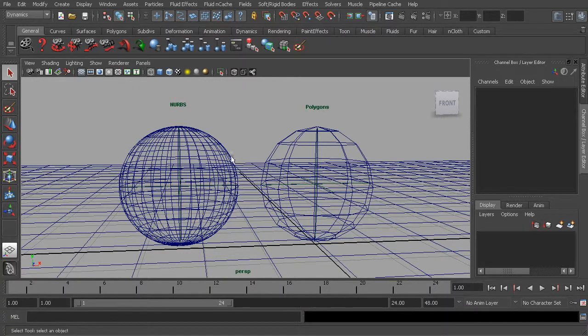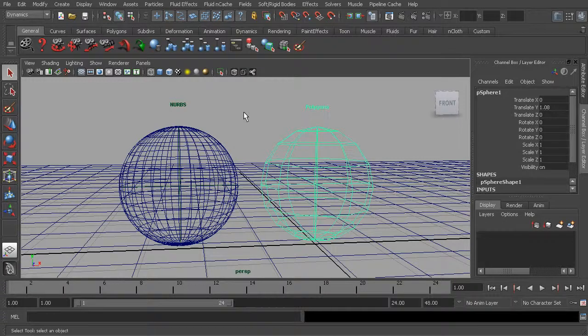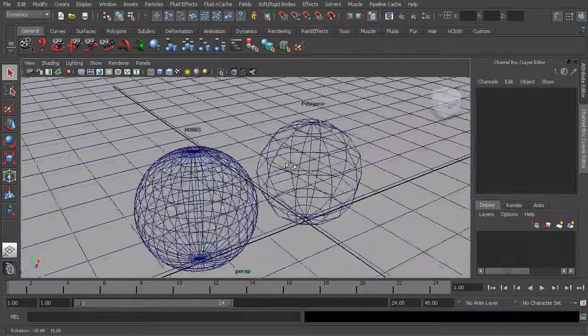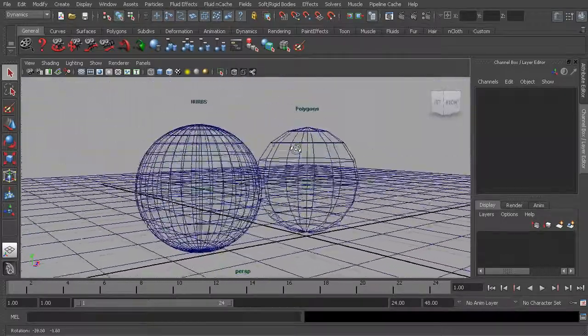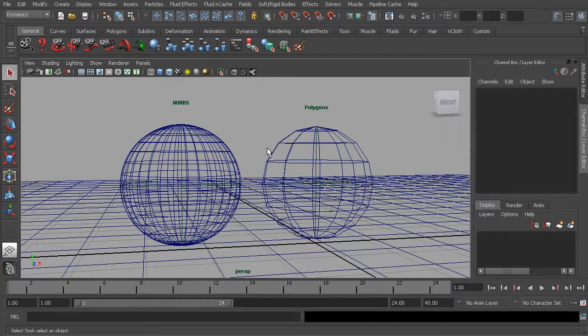Now, up to this point, we've been looking at objects in the viewport in this simple wireframe mode. Now, this is going to be the default shading method in Maya, and to switch between this wireframe and some other shading methods, we're going to need to remember a few simple keyboard shortcuts. So this is primarily going to be done on the number keys on your keyboard. So the 4 key is going to be the keyboard shortcut to switch to this wireframe view.